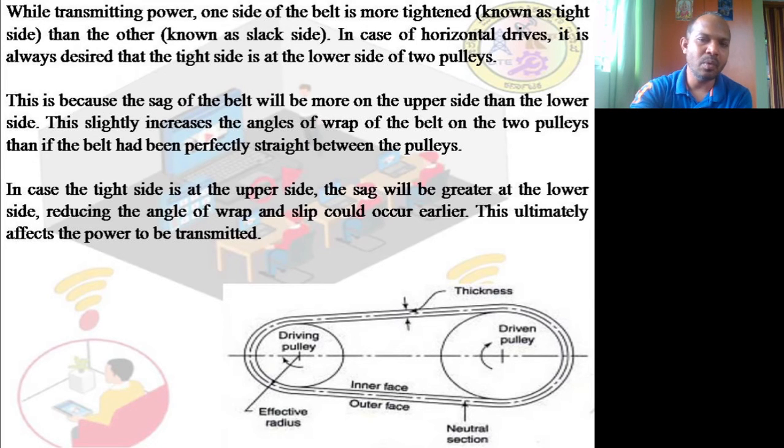So what happens is, only the inner surface of the belt will be exposed to the friction. It will be exposed because it is making contact, right? This surface is not making any contact with the pulley, only the inside surface is experiencing this friction. Whenever it experiences friction, it will experience heat. That means the failure of the belt may be more from the inner side.